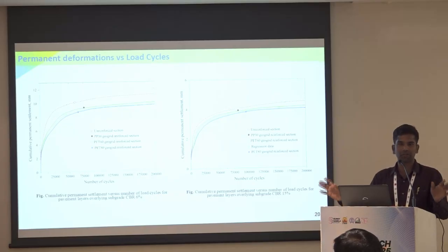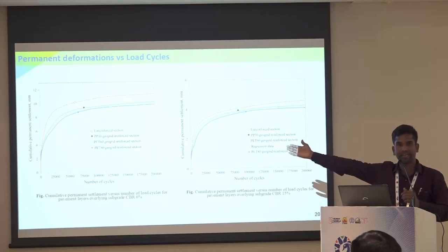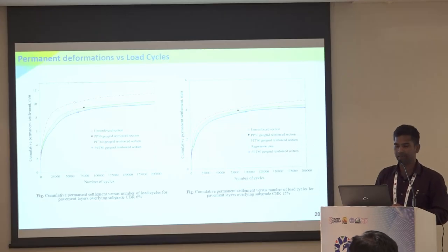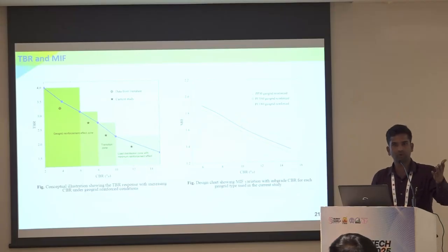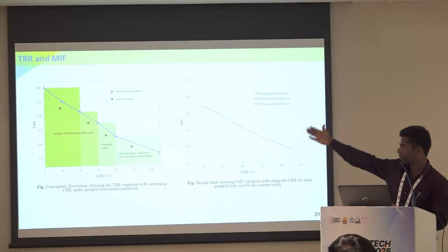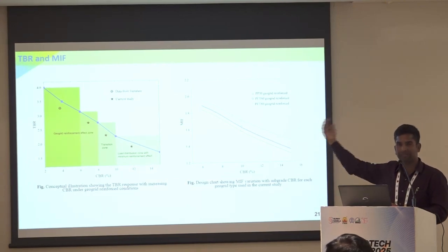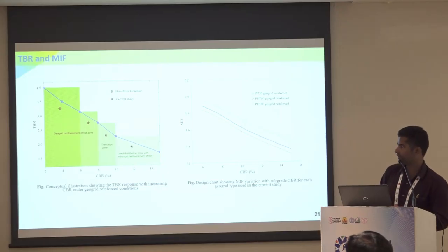And this became very challenging to compute at 20 mm. So after 3 days of continuous work, we stopped it and took a really close value at 10 mm rut depth to compute the traffic benefit ratios. That's what I mentioned in the earlier presentation, that it may not be appropriate to take rut depth at half or 1 inch. We have also come up with traffic benefit ratios for different subgrade conditions, including soft, medium and stiff. We found that as the reinforcement stiffness increases, better values come up, but it is up to our decision whether to use that value in the field, because all other parameters will be neglected through the traffic benefit ratio.